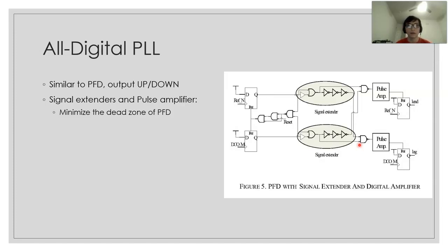The other component that has also been implemented is the PFD, the phase frequency detector, right here. It's quite similar to the flip-flop architecture, but in here, after outputting the up and down signals, they also added some signal extenders and other pulse amplifiers to minimize the dead zone of the PFD.